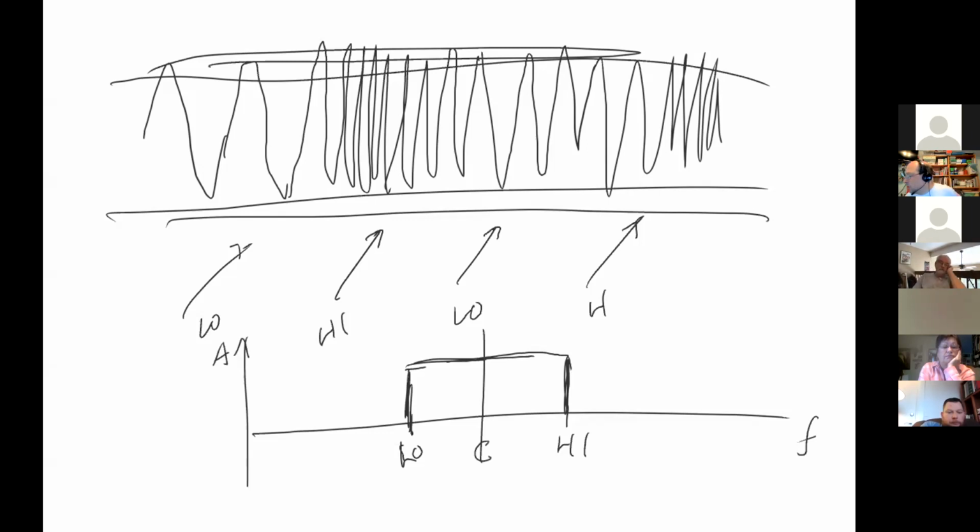How much signal is there? So this is actually known as frequency modulation. The amount of change in the signal from the center frequency that you get is known as the deviation of the signal, how much the frequency deviates from the center frequency.